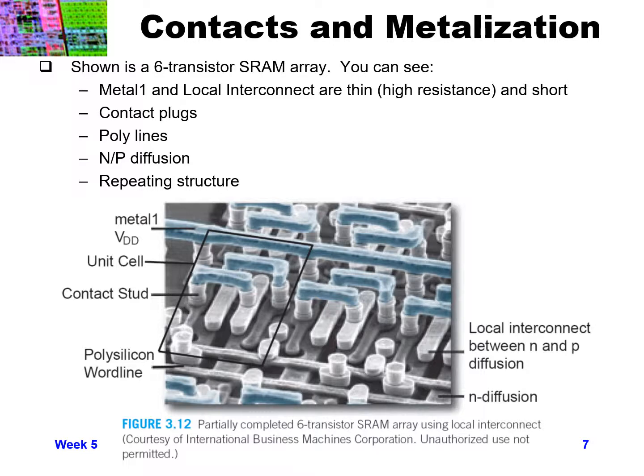So a lot of times when you're doing metallization, you'll have metallization that's mostly one direction. Sometimes it's defined to be exclusively one direction, and then alternating layers tend to go in opposite directions, so 90 degrees off from each other. So you can see that blue layer, then the layer underneath it is going kind of 90 degrees from it, but then they're connected between each other by those round plugs, which are the contacts between layers.